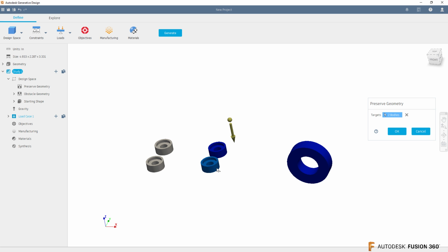These are the areas we definitely want to tell the software: the counterbores, where the screws are going to mount, and where we're going to put the loads for this part. Hit OK on that, and that turns green. That's the setup for this in regards to the geometry.